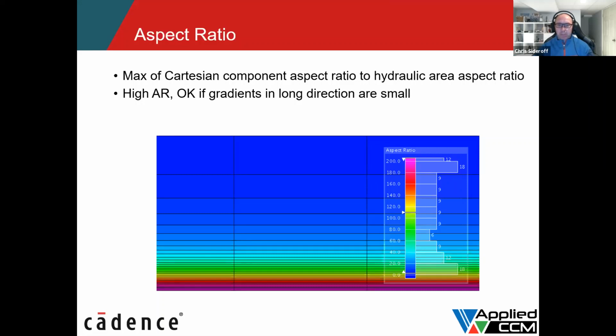I would say it's probably more common, or at least where I see it, to be in the marine world where we want to run not model scale but full scale simulations, where a ship or a submarine has a very high Reynolds number, but yet we're trying to resolve the mesh into the wall, and we're trying to keep the mesh count down. It's not uncommon to encounter aspect ratios that are well over 10,000, and those can be challenging.